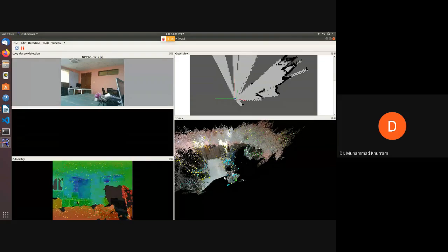A self-driving vehicle consists of different modules. Each module needs to perform its specific tasks. The modules would start from hardware modules, which are basically the sensor modules, and ROS is going to play its role in each of the specific modules. When we have attached different sensors to a vehicle, ROS is going to help acquire the data from each individual sensor, synchronize those values, and pass it on to the filtering modules.